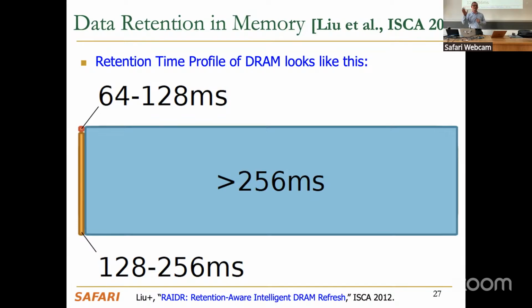And these are really great questions because this sort of behavior exists in any type of memory, not just DRAM. It exists in flash, which we have a lot of studies on, but we're not going to focus a whole lot, at least initially. It exists in other memories like phase change memory and RRAM, in different ways. In that case, it's not charge, it's resistance levels. Charge leaks, but resistance also drifts, meaning you have a resistance level, but over time that resistance level changes, which is fascinating also. Okay. Any other questions over here?